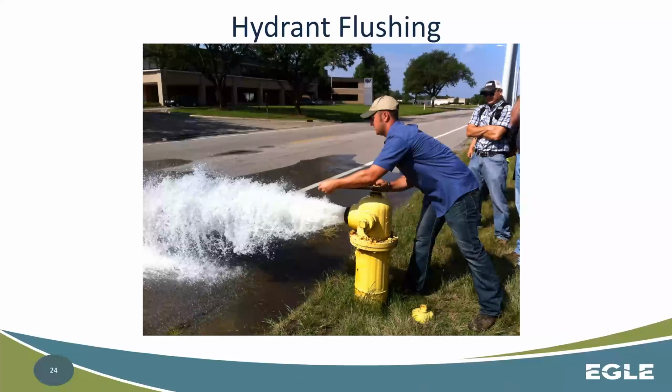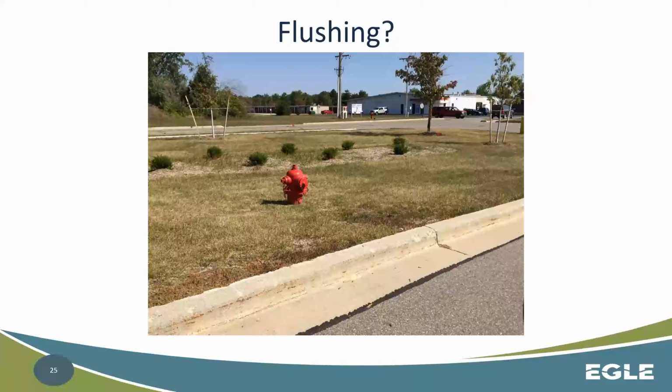This specific hydrant, as you can see, is causing an issue in the roadway. So you have to be paying attention to where the water that you're dispersing out of a hydrant is going, and properly closing traffic or avoiding traffic issues such as this, making sure that you've got the right controls in place.